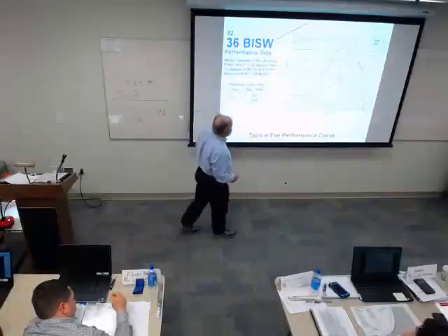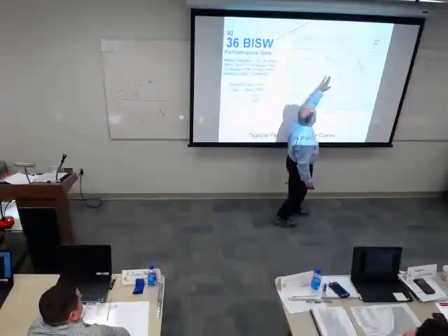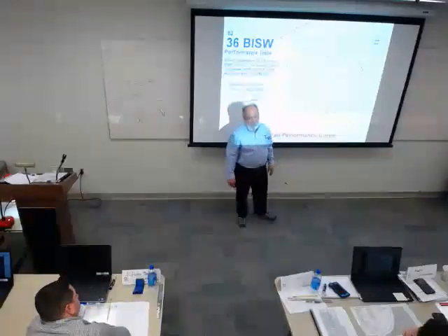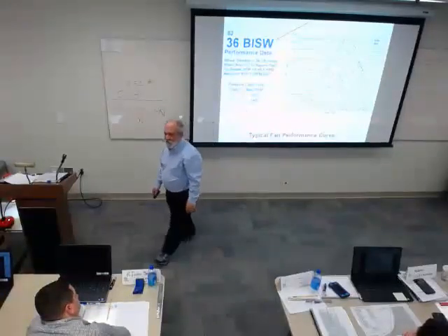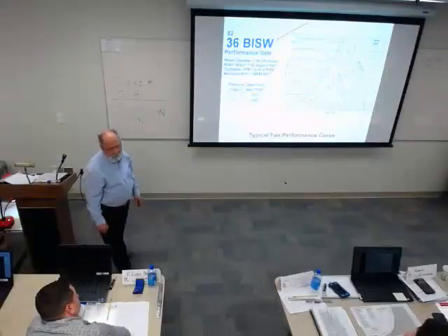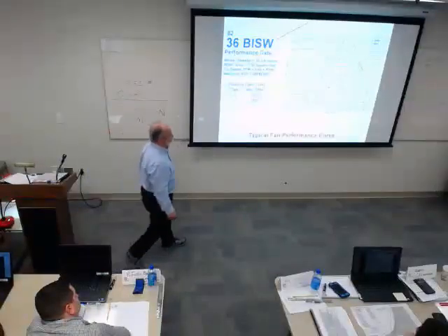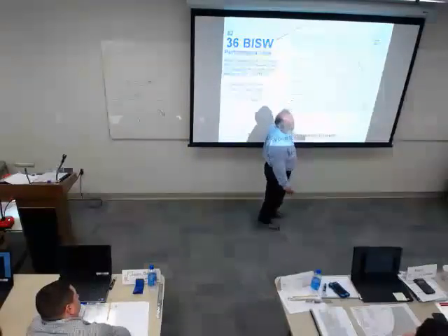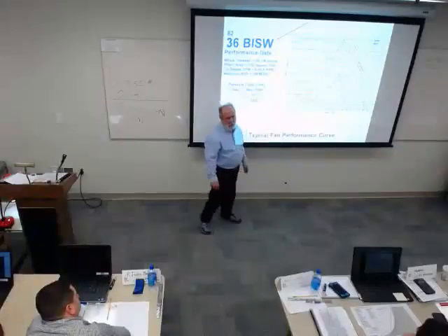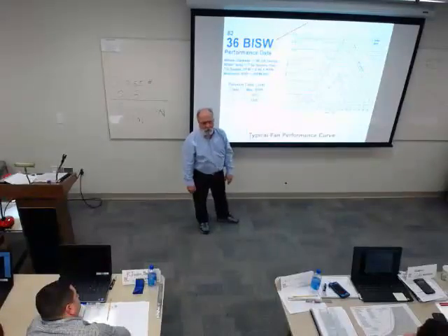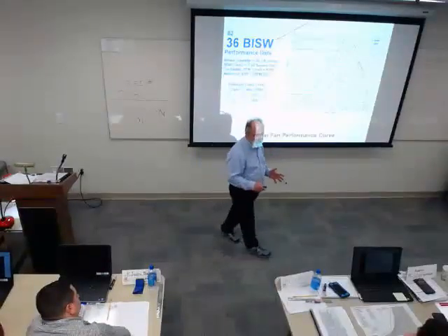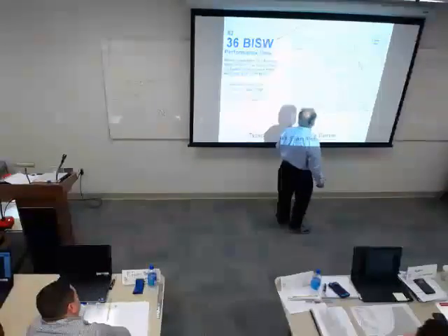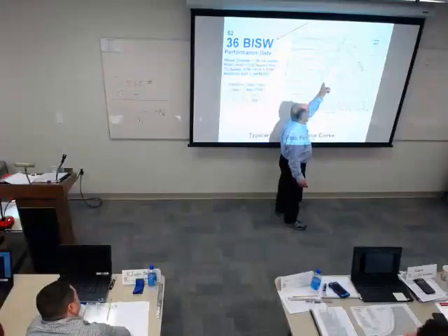So this line right here is the one that you never want to go on this side of. The reason is you get into what we'll call stall territory, because you don't have enough mass through the fan to maintain the airflow at those pressures. You see it stall out and go flat. It's really worse than that, and you'll get the fan going loop, loop, loop, loop. That's because of the air going in and out of the fan vanes. In time, it can fatigue.